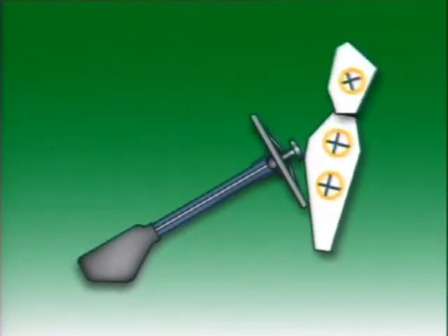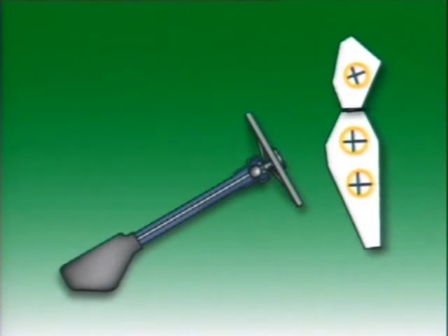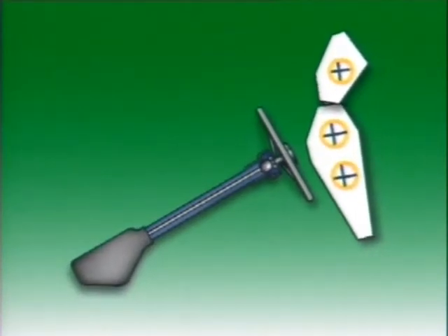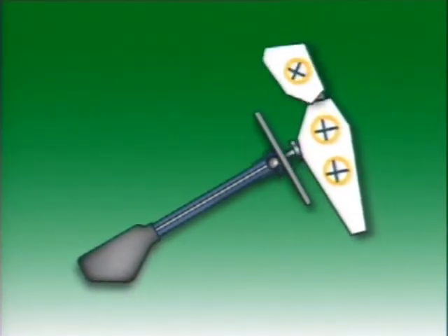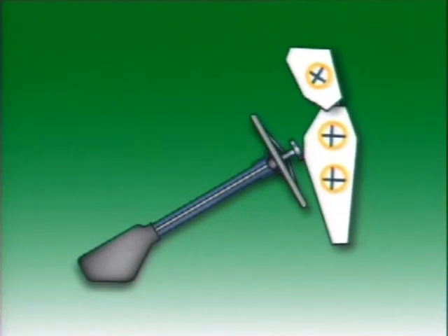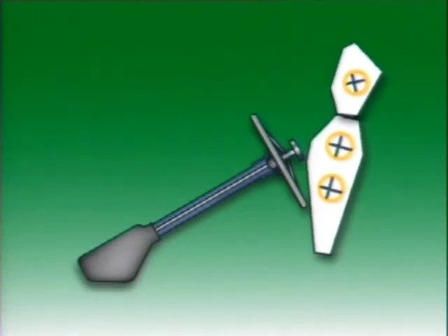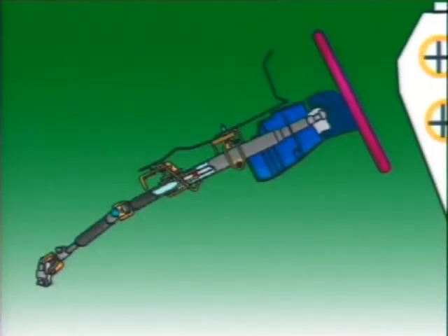In many frontal collisions, however, this caused serious injury to the driver, partly because it was forced back towards the driver's head and partly because the sudden stop forced the driver onto the wheel. To reduce this hazard, some steering columns are fitted with collapsible sections that protect the driver.